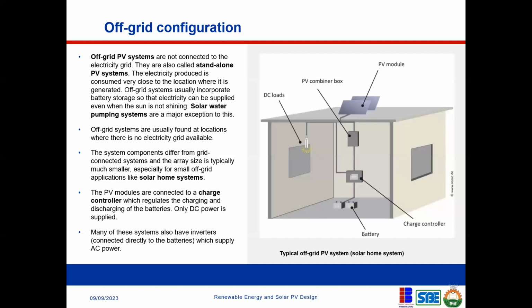What your charge controller actually does is help stabilize the voltage that comes into your battery, because if you don't have this charge controller, your solar panel voltage can vary, right? But you need a charge controller to keep the voltage constant depending on the voltage of your battery.